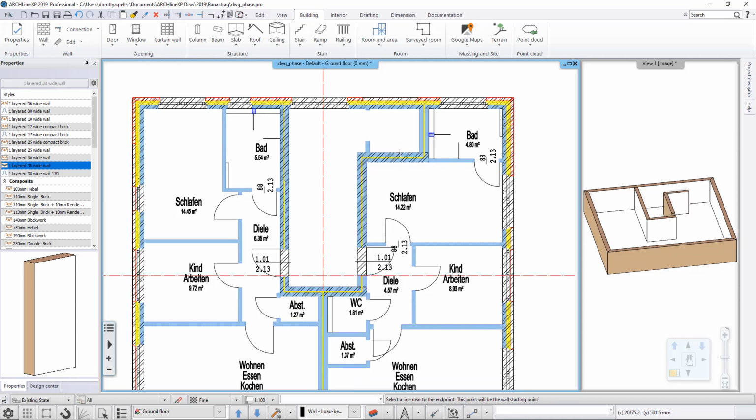Now this is the time when I have to care about the partition walls as well. But one important thing about them is they are thinner than the rest. I do not need to take care of the thickness. I just have to click on the right points and the software is automatically going to take care of the thickness and the height values.